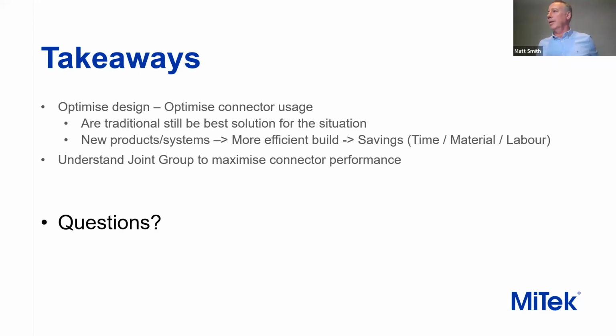One question that I half answered for you, from Charles: is there a mandatory requirement to ensure nail spacing and edge distance are maintained in triple grips? I would ensure that your edge spacing for the triple grip to the edge of the timber is as per the guidelines, but the actual nail fixings within the product themselves have been designed and tested for each of the components.